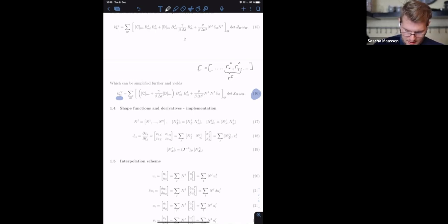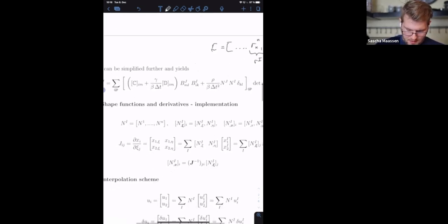Anything that we have to discuss in here? I think not, because D over here was shown in the constitutive law. We have these factors over here, which appear to stem from the Newmark time integration and the concerning derivatives of Newmark parameters like the acceleration or velocity with respect to our degrees of freedom.